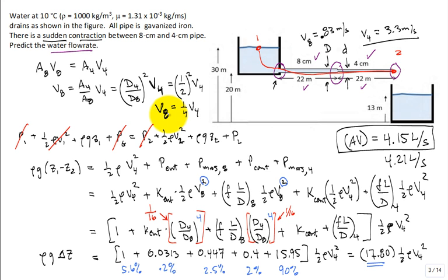They will jump so fast to start to converge. If you do it 3 times, you'll be amazed. It'll go right fast for this problem for sure. Okay? So the V's have to start. Well, the friction factors will converge. The Reynolds numbers will stop changing. The flow will stop changing. Right. Yep.